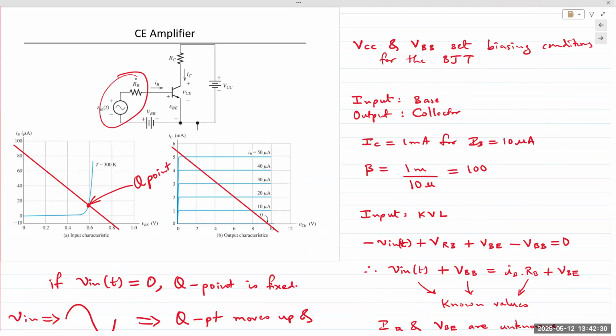We're not doing the analysis of the gain equation for this circuit, but the end result of this kind of bias is that the amplification, or the gain factor, depends on the beta of the transistor. This kind of DC biasing is known as fixed bias, or fixed base bias, and it depends on the beta of the transistor.